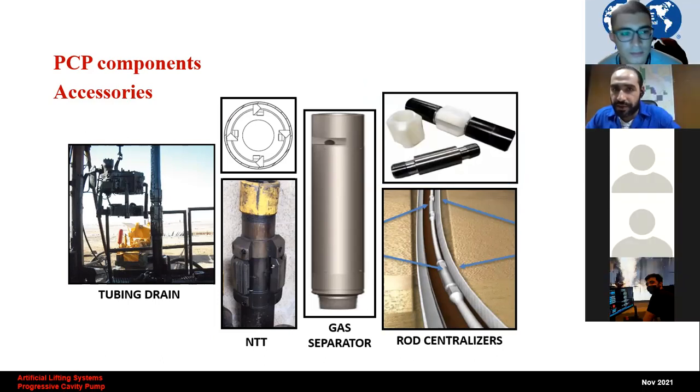I can say it clearly, it will eat the tubing wall and cause premature tubing failure or sucker rod failure, or even both. So rod centralizers are very, very important in horizontal or deviated wells.